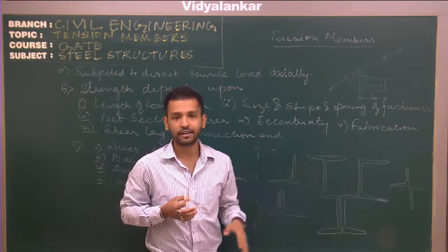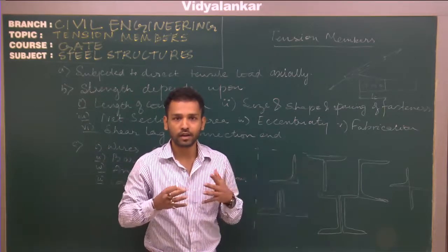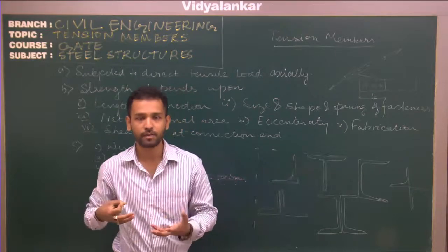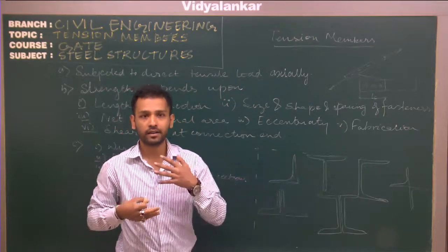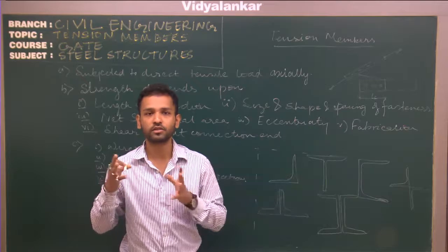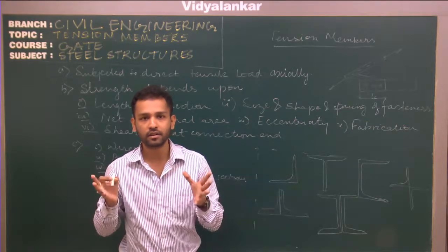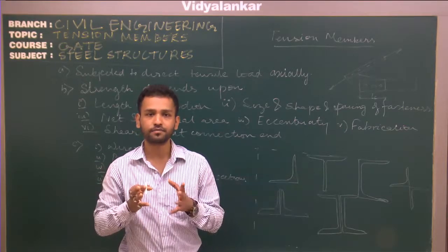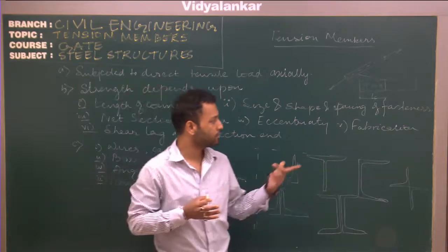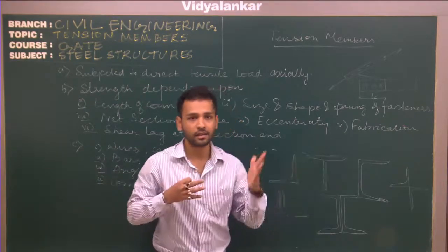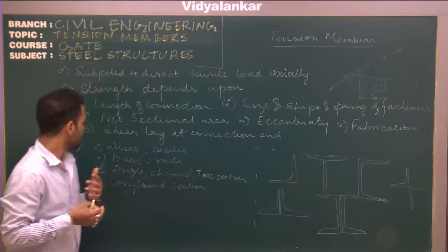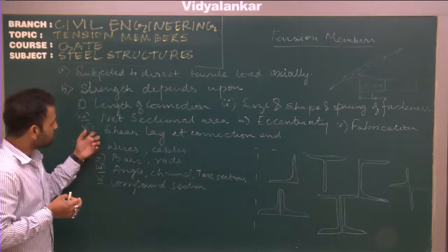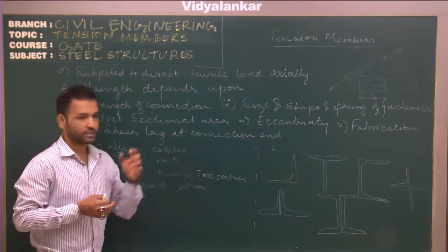But for a field fabricated member, where the work has to be done in a very short span of time and where the adherence to the codal provisions is not so high, the standard deviation is high, and hence the strength of the tension member, if it is field fabricated, will be lesser than the shop fabricated one. Then the last and one of the most important is the shear lag at the end connection.